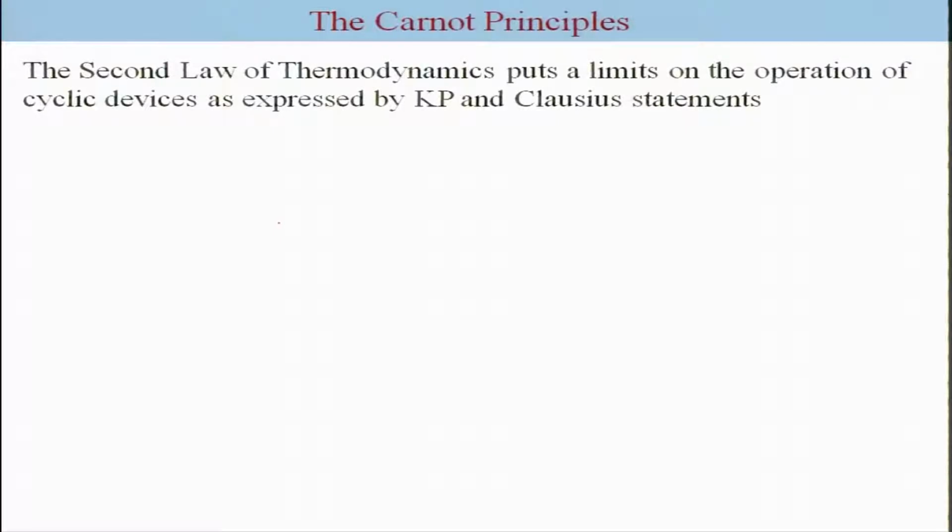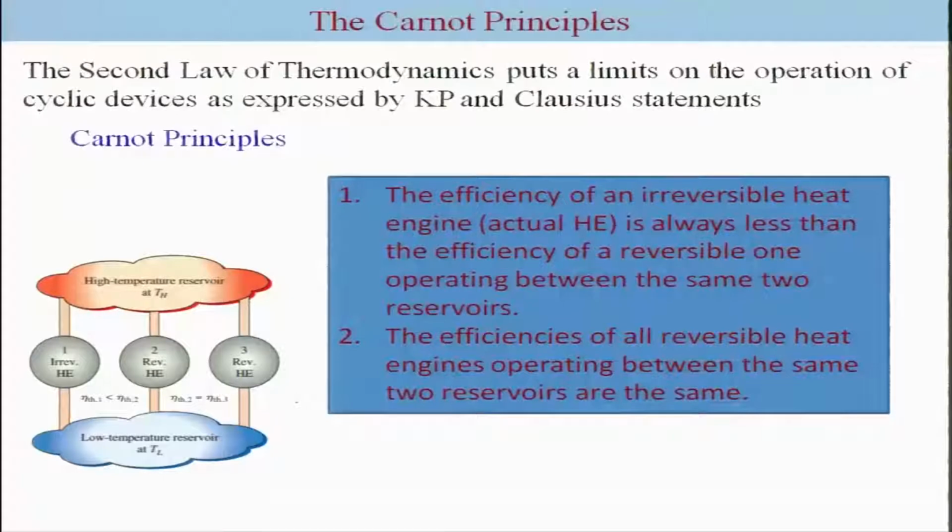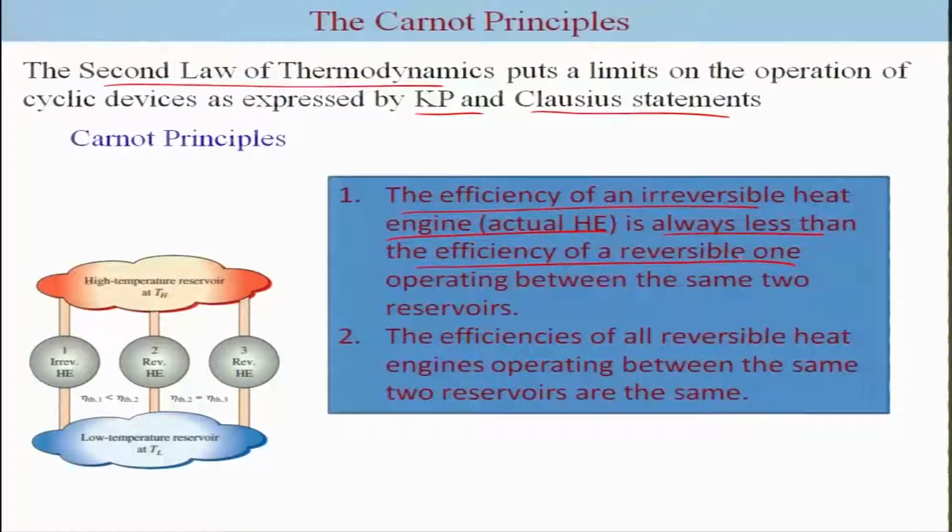So, what is the principle of Carnot based on this analysis? Making use of the second law of thermodynamics and the Kelvin-Planck and Clausius statements, the Carnot principle says that the efficiency of an irreversible heat engine or actual heat engine is always less than the efficiency of a reversible one operating between the same 2 reservoirs.